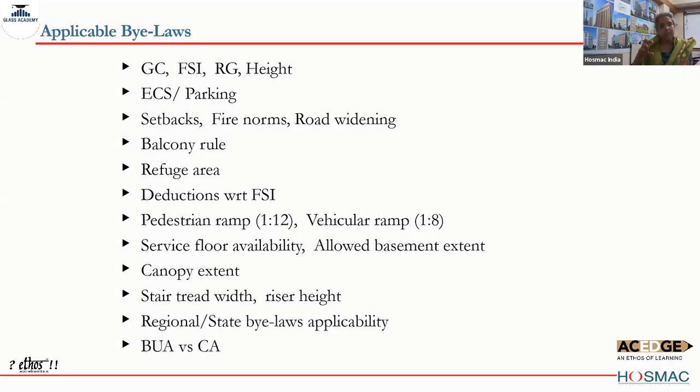We calculate how many spaces of car parks we can provide per 100 beds in a hospital. For setbacks, there is a general rule, h/3, but like in southern India and Kerala, the h/3 is what really determines how much building you can build. There is no FSI or FAR in Kerala. So these norms one has to sieve out and see what fits as per what governs. So there are fire norms which are all India basis.